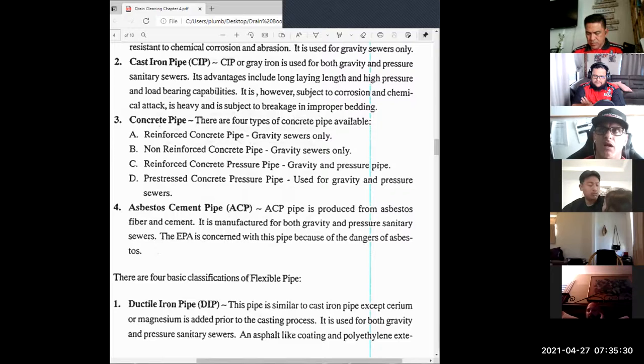But I think the process when instructing a customer, let's just say you're dealing with an asbestos sewer main, the proper procedure at the time would be to abandon the main. You could use one of our technologies, whether you're lining through it, or you dig next to it and install a new main. You could burst through it, because you're not in the area of cutting. You can cut back where the cast iron connects to it.